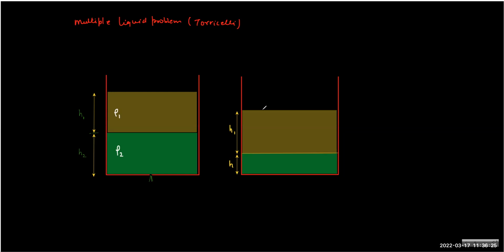So now, let's say I want to know the velocity of the liquid coming out at some random instant. I want to know the velocity right now. So I can apply the Bernoulli equation, for the sake of simplicity, between points one and two. And that's very interesting, that when the liquid crosses the boundary of a vessel, that is sufficient to accelerate it to any velocity.